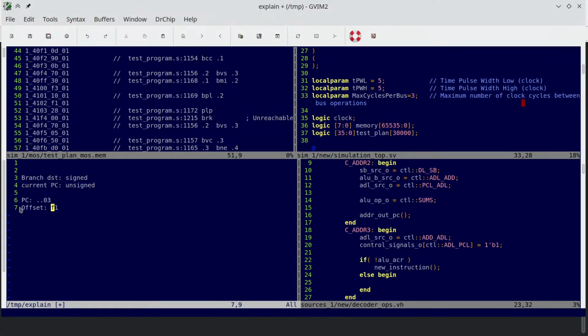So we need to subtract 15 from 03. If we're subtracting, but if we just add it, we see that there is no carry, right? We get F4, no overflow. Because we're mixing signed and unsigned, our logic needs to be a little different.